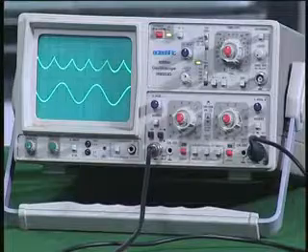So we have seen the demo corresponding to the two circuits. One is the precision half wave rectifier using an operational amplifier, and the second is a precision full wave rectifier where we have used a half wave rectifier along with the summing amplifier to cleverly obtain a full wave rectified signal. This is all discussed in many of the standard textbooks.